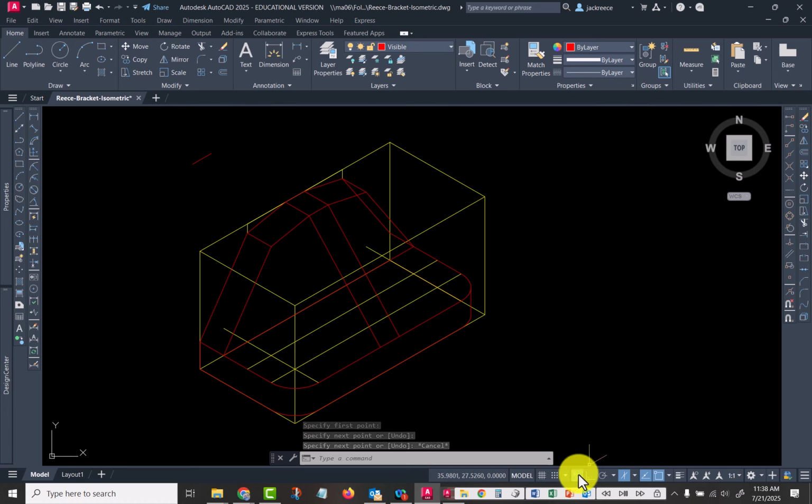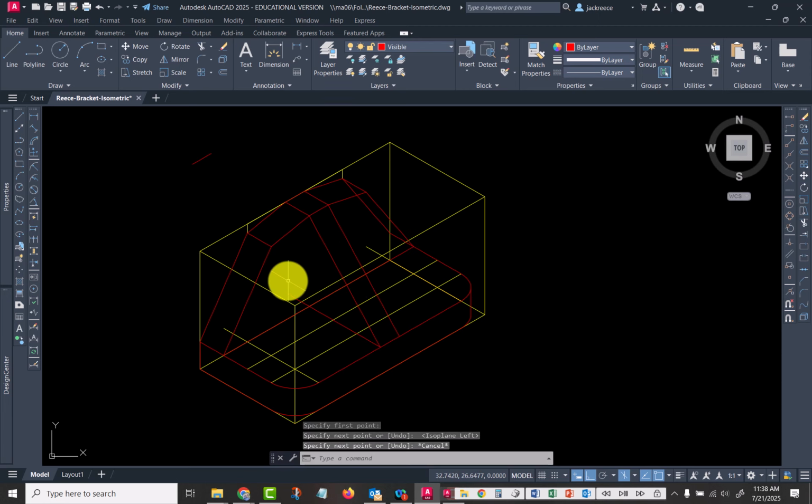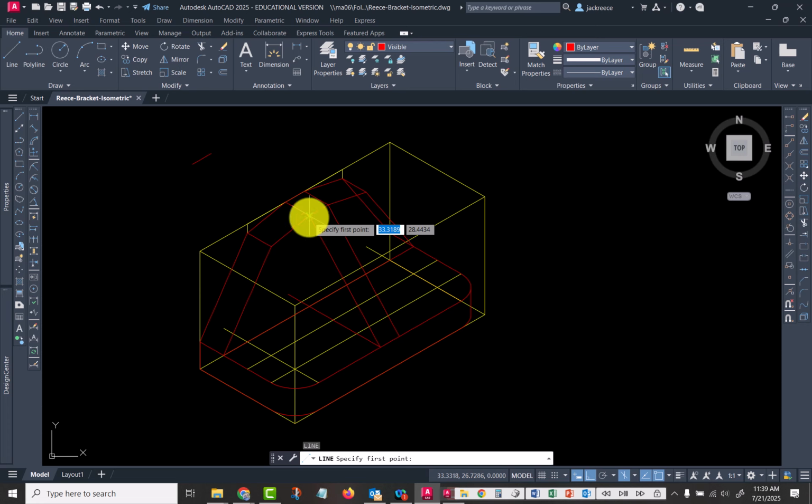And so let's turn our ortho mode back on, and we'll draw this line from here back. Oops, change my plane. I'm going to draw it a little bit long so I'm not getting an object snap there. And then we'll draw a vertical line, which would come to there. And now I can trim those out. I've got that.